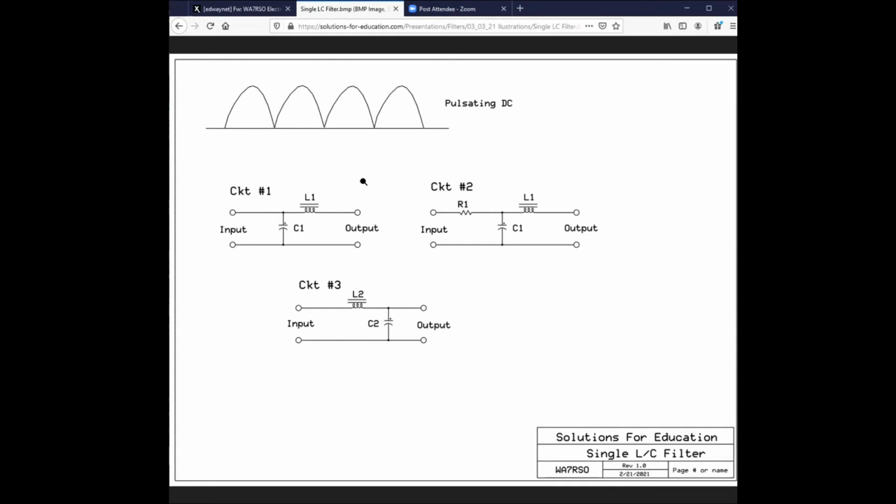Now, here's something that you may not know. The epidermis, which makes up your skin, if you will, has 2,000 times more resistance than the inner body does. Normally, if you go hand to hand with an ohm meter, you'll measure about 200,000 ohms. If you happen to puncture yourself and measure the inner body, it's only 200 ohms. Big, big difference.